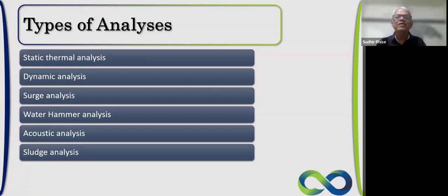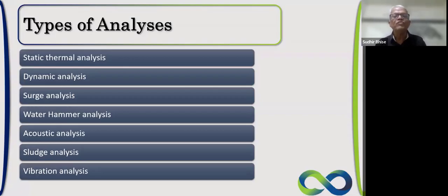And finally, it is the vibration analysis. Whenever we have large diameter piping for compressors, turbines, and pumps, there we go for vibration analysis. Now, out of these analyses, the one that we are concentrating on is going to be only static thermal analysis.